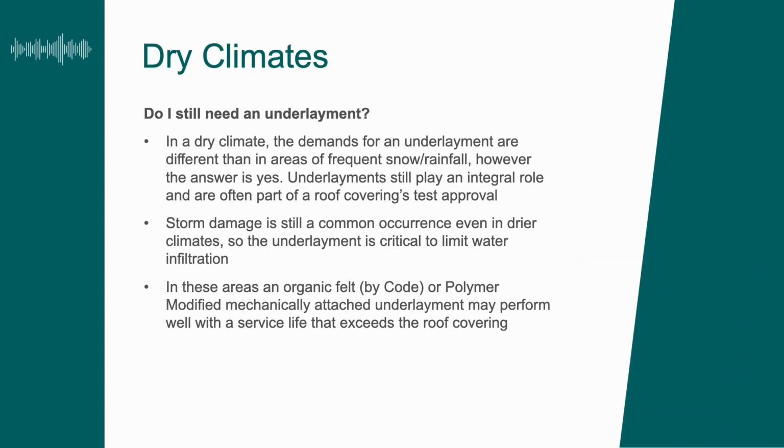Some of the guys in the Southwest have this mentality: why do I even need an underlayment? Because it just doesn't rain much in the Southwest, Southern California, Southern Arizona. It does rain, but it's not as frequent. You don't see the elements that you do in climate zones that are beyond, say, 3 and higher in the country. But underlayments are still important because they play an integral part of any roof covering.